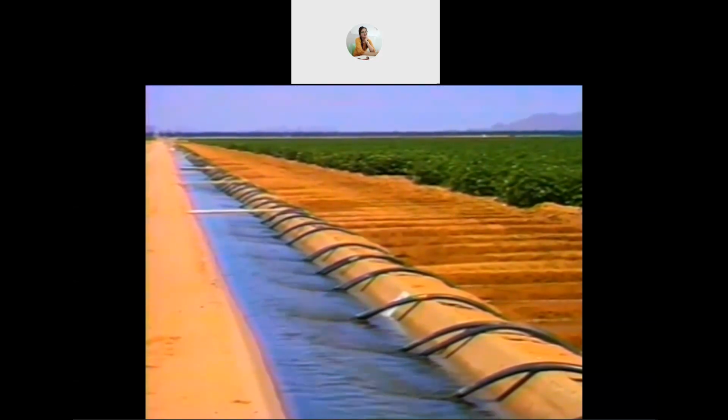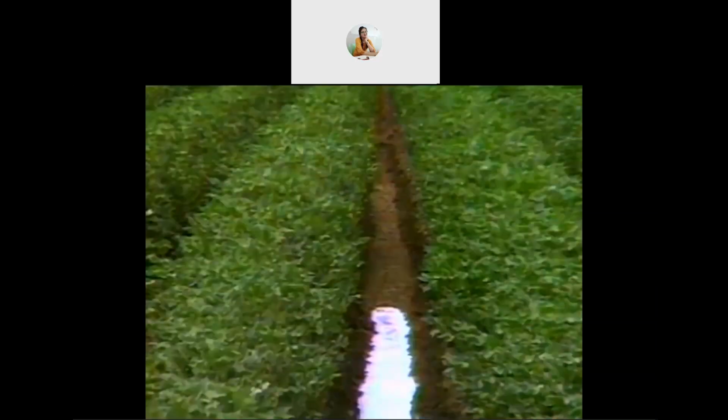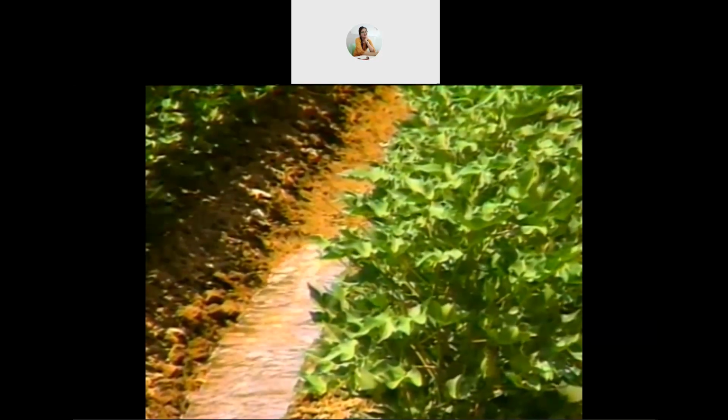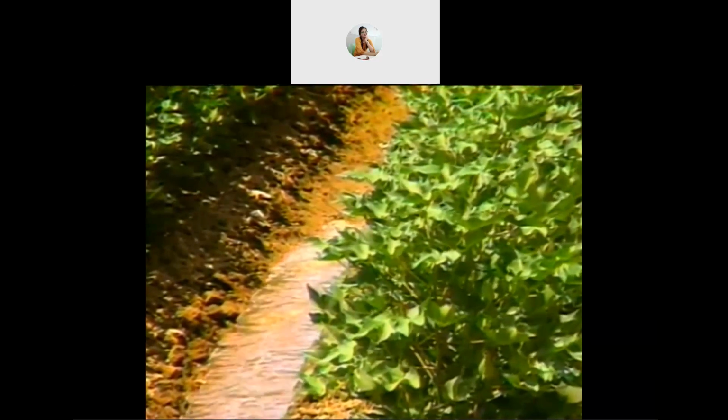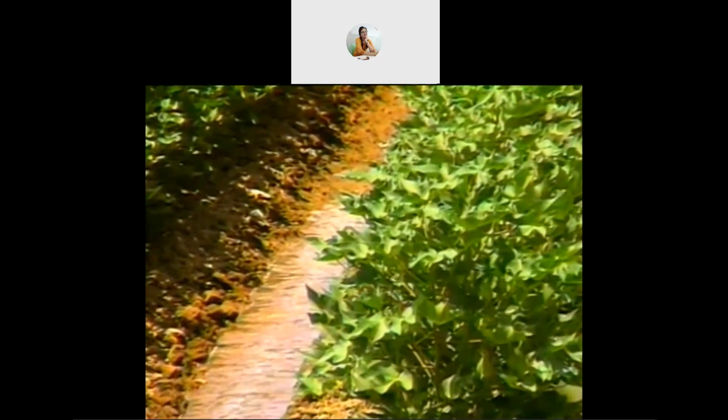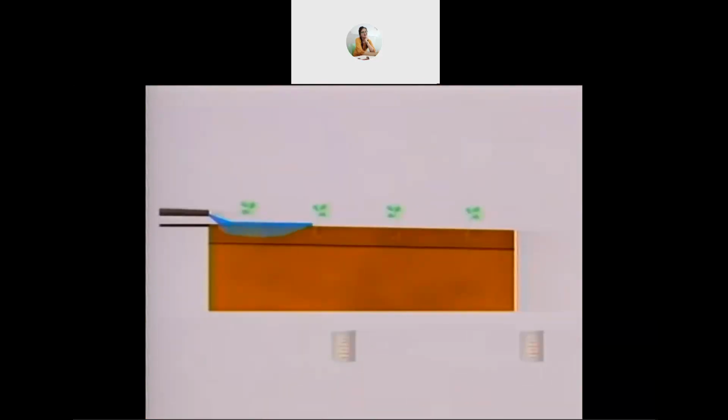Once you start an irrigation, keep track of how the water is moving down the rows. There are some ways you can change your irrigations to reduce water use. These methods will only work on some fields, and possibly only during part of the season. You should talk to your farm manager if you think one of these methods might help. Remember, if you irrigate with a low flow rate, you will have a smaller amount of tailwater runoff, but will lose more water to deep percolation.